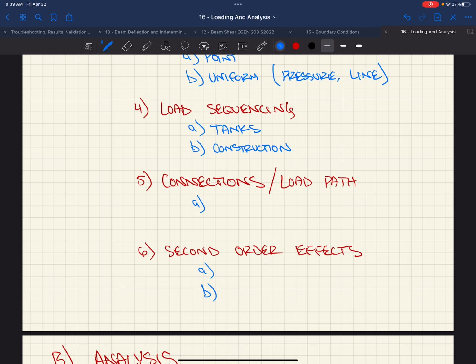Well, unless you're ripping out tons of concrete. Yeah, I mean, like you build a tank, you have to test it, right? Well, there are some of those sequences you were saying, and then rip all that out. Oh yeah, the camber, yeah, for sure. Yes, that also raises costs. But so you end up just upsizing the beam so you don't get as much deflection in the first place, which adds a little bit of cost, but then the contractor doesn't have to think about that, right? As they move through it.